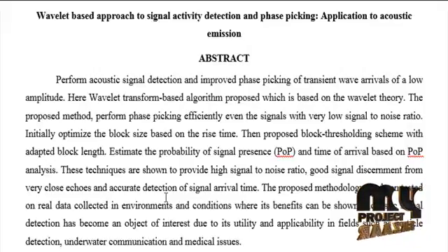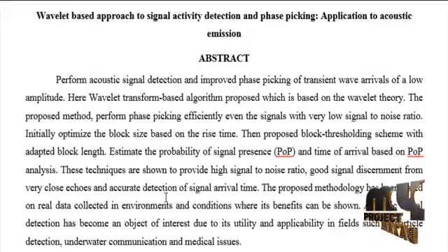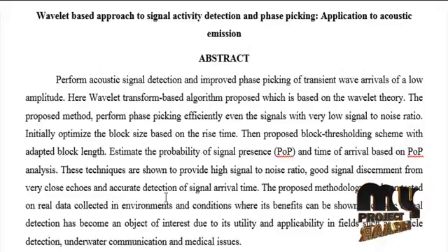Time of arrival is the travel time of a radio signal from a single transmitter to a remote signal receiver. Time of arrival uses the absolute time of arrival at a certain base station rather than the measured time difference between departing from one and arriving at the other station. The distance can be directly calculated from the time of arrival, as signals travel with a known velocity.